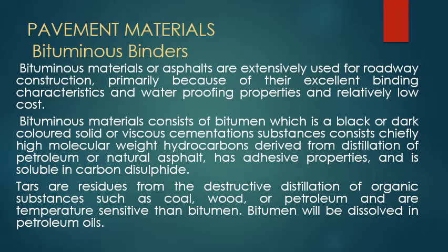That is very important, because when we come across water, it should give good bonding between the aggregates, and it is useful for the construction of pavements. These bituminous materials are thermoplastic hydrocarbons which possess high molecular weight, and they become soft on heating and harden on cooling. Have you observed that?